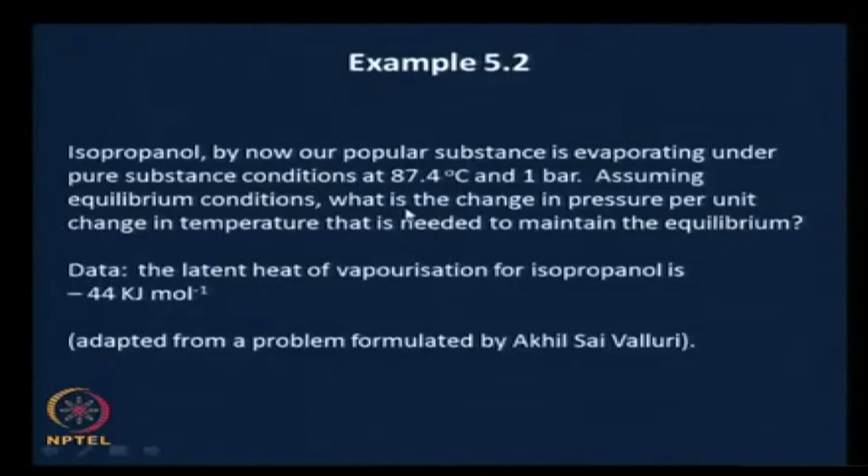You would have had time to think through this, and hopefully the thought became focused towards recognizing that this is a substance evaporating under pure substance conditions, therefore it is changing its phase from liquid to vapor, therefore it is a case of phase change, and what is required is change in pressure per unit change in temperature that is needed to maintain equilibrium, therefore the whole process is under equilibrium conditions.